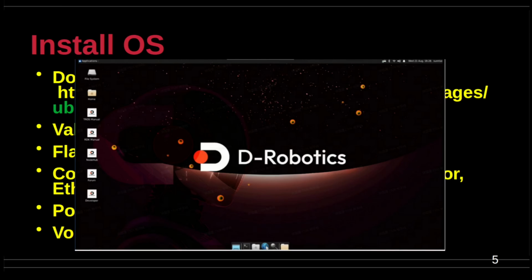While there are many ways to flash the image, I used the Raspberry Pi imager for this purpose. After flashing the card, insert it into the slot on the board. Connect the peripherals: keyboard, mouse, display monitor, and Ethernet connection. Then power the board. Monitor the status LEDs. After the boot process is complete, the monitor should display a recognizable background screen.